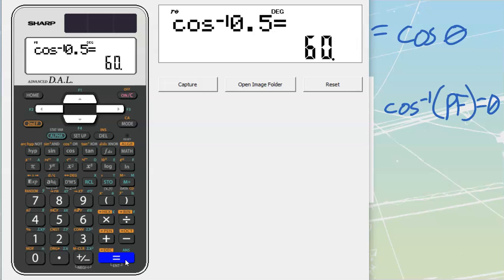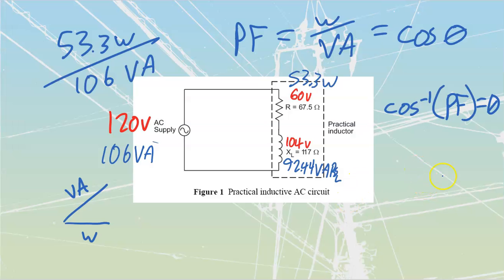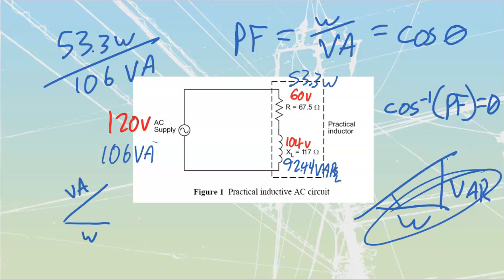Power factor is just going to be the ratio of our watts to our VA. Now, they're going to give you a couple more examples that they're going to ask you about, where they say, hey, we've got apparent power, which is what our VA is. We've got watts, which is our true useful work. Find me my power factor. And at times, they can even say, look, I haven't given you your VA, but if I give you your VARs and your watts, you should be able to either use tangent to create an angle, or just punch those two values together into your calculator to get a value and an angle, and then that value is going to be your total VA, and the angle would be whatever the circuit angle itself is.